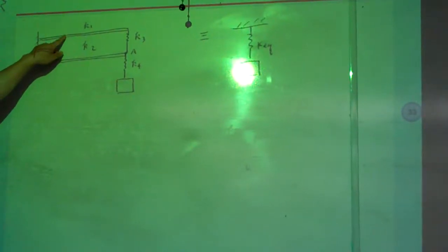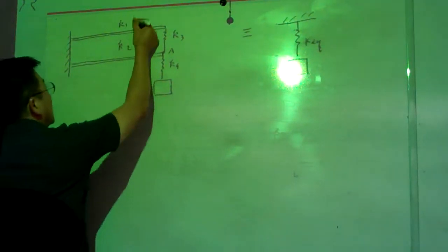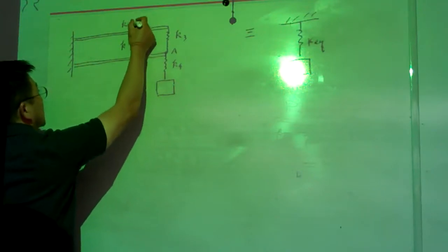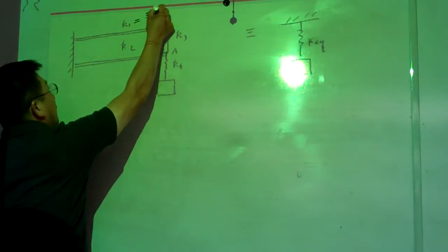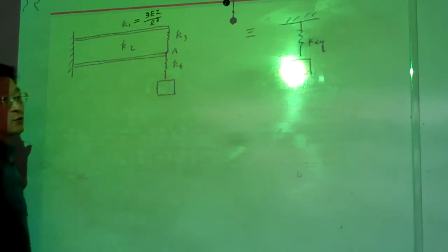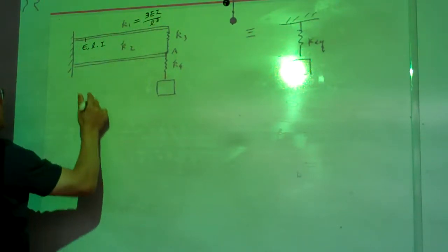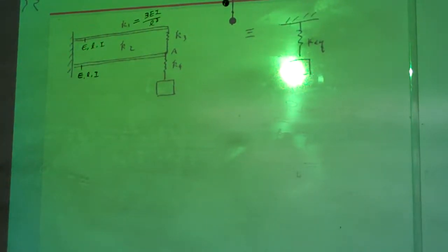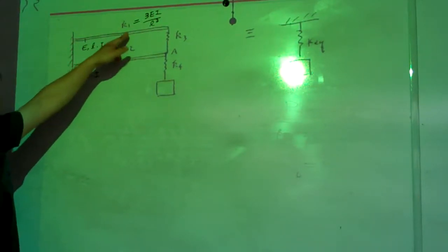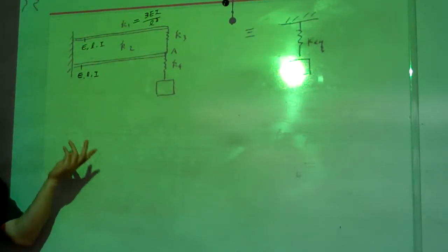this is an elastic beam. So basically, you can find the equivalent spring constant. For example, this is a cantilever beam, so it has a template like 3EI divided by L cubed. If we assign this EI, then you have this one. If this is another EI, then K2 will have the same pattern. So this is one spring, this is a second spring, a third one, a fourth one. There's a total of 4 springs connecting in such a case.